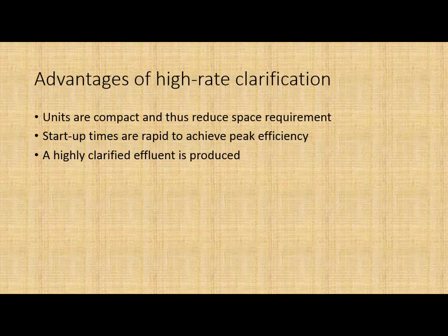And the advantages of high-rate clarification: the first one is that the units are compact and thus reduce the space requirement, since big cities are always lacking space, and the smaller the facility, the better the usage. The second one is that the startup time is rapid to achieve peak efficiency. The third one is that it will get a highly clarified effluent product.